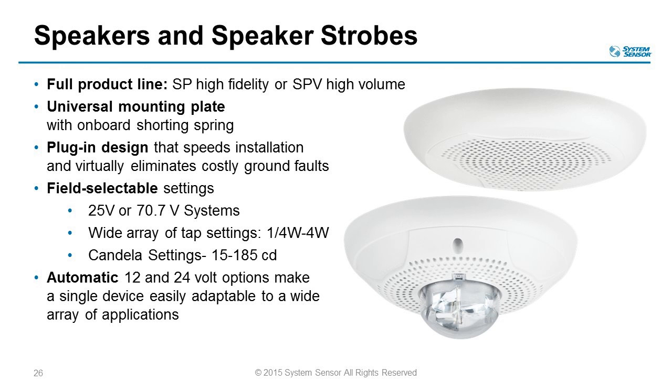Our Spectra Alert Advanced line of speakers take less room in the electrical back box and are one of the only products in the market with a plug-in design. This really minimizes the ability for pinched wires during installation and timely chasing down of ground faults. We also offer accessories if you need a little bit more room in that electrical back box.